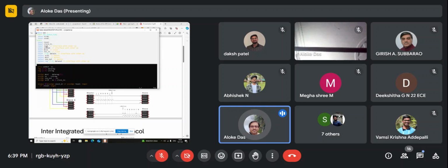And there are two more signals, load and unload. Why? Because you are sending data from the SPI protocol chip. So where does this data come from? It will come from somewhere, right? Generally this chip will be part of your SoC system. Like if you give it to me, I'll hook it up into a microprocessor or any other bigger thing where other things are happening and some data is generated.